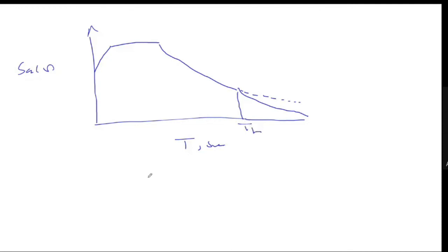So there is also a corner time period, or TL, where the spectrum changes its shape, and it reduces by T squared rather than T, which is basically decaying in this branch. Okay, so again you can see that this region is what is called the acceleration sensitive region. This is the velocity sensitive region, and the other one here is the displacement sensitive region.